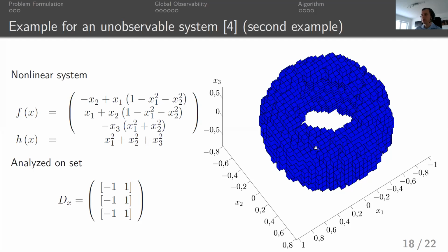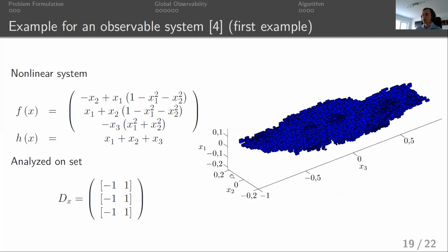With this data, we can evaluate why the system is not observable. In this case, it seems that the quadratics of the output function are an issue. If we remove them, we get a different picture. Now we can see all intervals for which observability could have been proven, and we also see more than that.